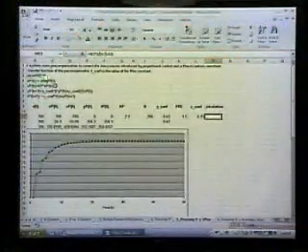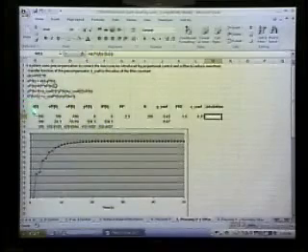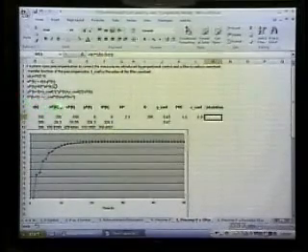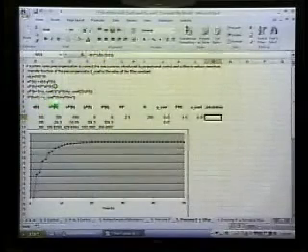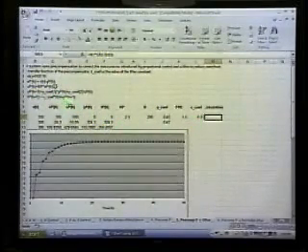Here we've got our reference input, which has to go through the precompensator. The control error is computed as before. All this stuff is as before, but we've added this T part down here, where T at time k plus 1, for this proportional controller, is equal to what it was in the last time step, T at k, times some coefficient, plus whatever the y output is.